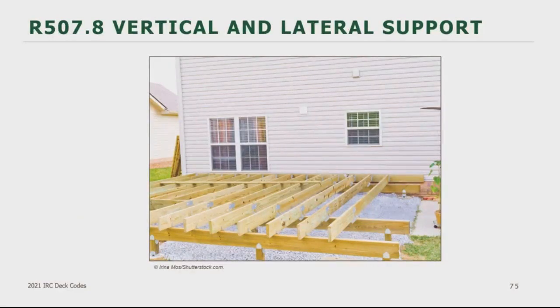Just a quick note here, I mentioned very early on that the existing house can remain as is under the code under which it was built, until an addition or an alteration makes it less compliant with the code. Prior to this deck being installed, the windows on the left-hand side of the existing house were probably just normal windows. However, by installing this deck, you now have a walking surface very close to the bottom edge of the windows. So those windows will now be required to be replaced with tempered safety glazing if they didn't already have it.